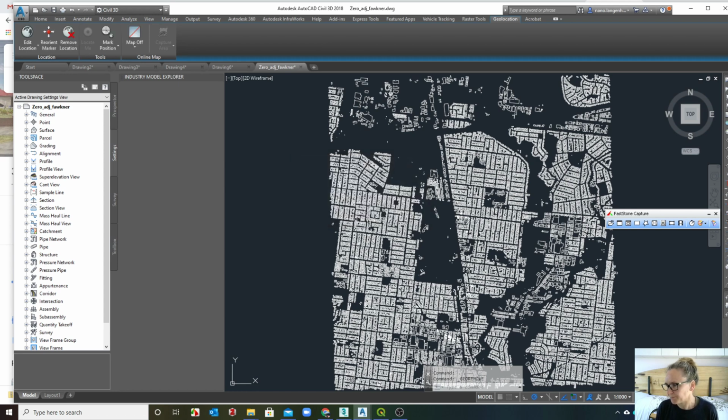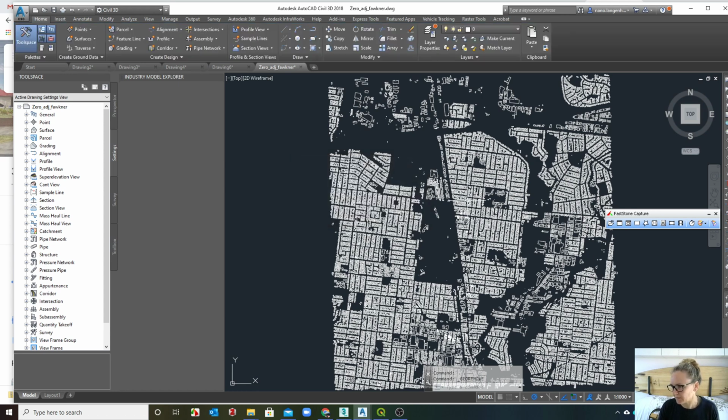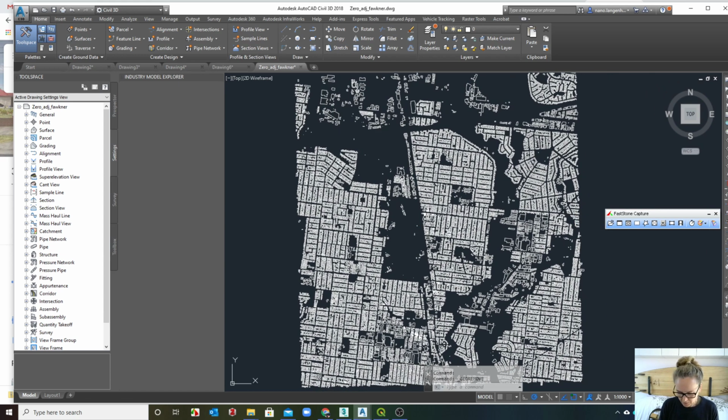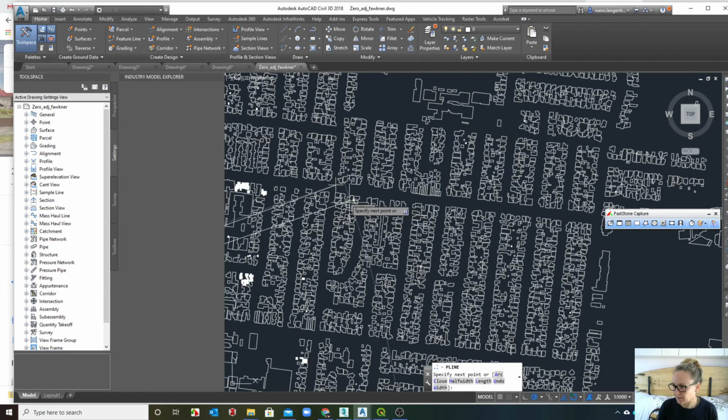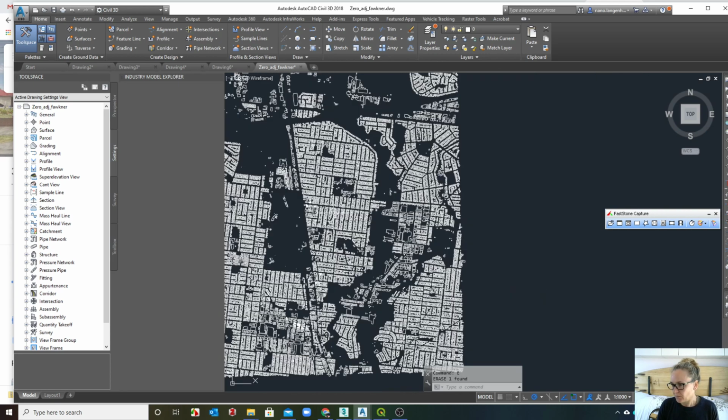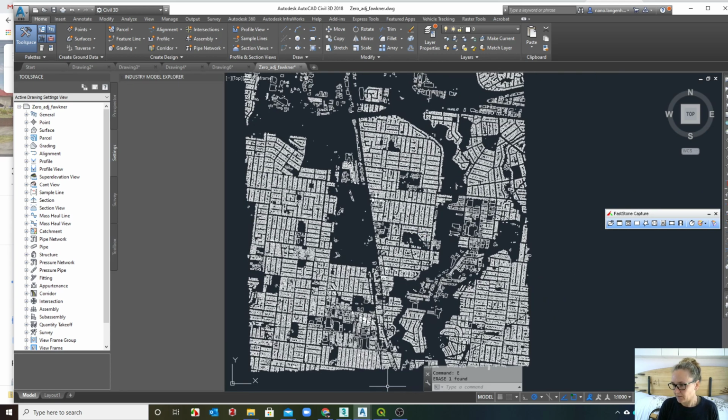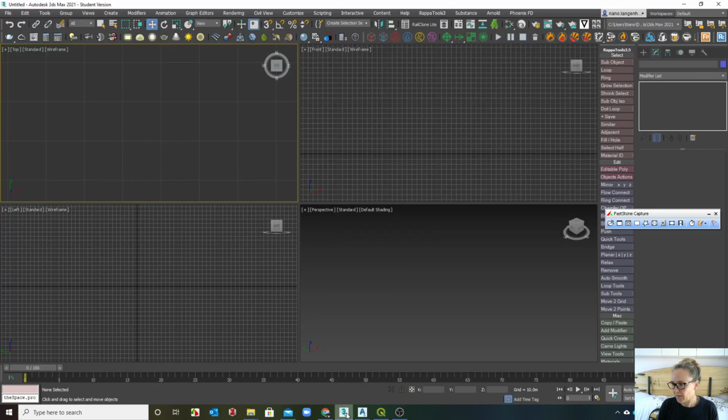Let's say yes, because we really don't want this drawing to be geolocated. Because when I want to do my polyline from 0,0, I want it to be doing exactly this. I want it to think that the centre of the world is that point I gave it as the export point. So that's excellent.